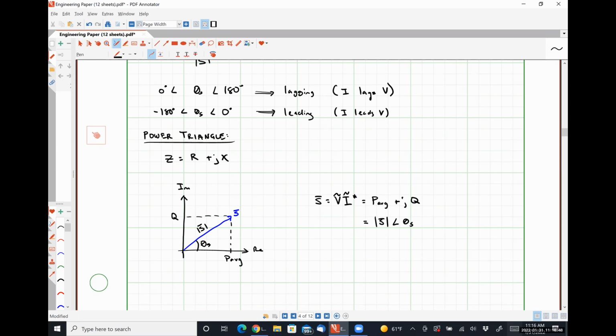Because it would require continuous operation of all of the inductive loads in your house to drive it that far, which is why I'm saying something like a washateria, where all of the loads are effectively induction motor related and lots of them are going to be on at any given time, is likely going to drive your power factor down. Right?